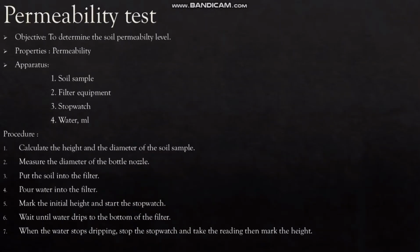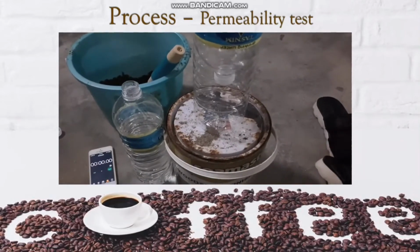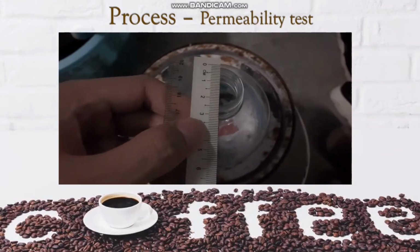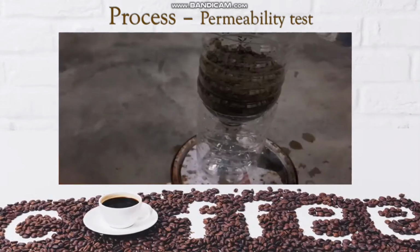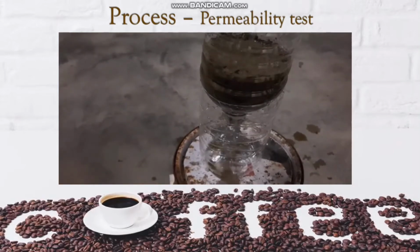It's the permeability test. Okay, here are the materials. We need to find the diameter of the nozzle, which is 2.5. The diameter of the water bottle is 8 cm, because it is the same as the soil. After we compact it, it needs to be compacted first because we don't want the soil to fall into the bottle.